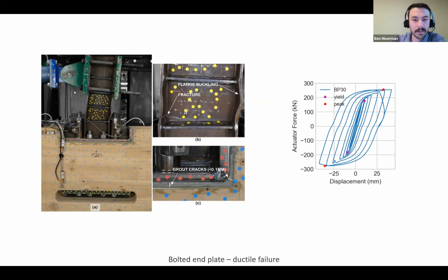So we did a ductile link beam, and we can see our grout here perform really nice. And I realize I forgot to explain why we have the grout there, so I'll do that now. Basically, this system is really sensitive to getting that connection dead tight, and to get proper tolerance in the steel and in the timber, it would just be too cost prohibitive. And I'm not even convinced every fabricator could hit fraction of a millimeter tolerance. It's just not practical. And so what we did is we oversized that joint by 10 millimeters and then just poured some base plate grout in there.